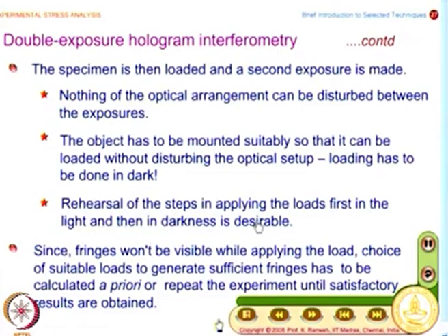So, when you want to record a hologram, you have to do this practice, and from the loading point of view, since fringes won't be visible while applying the load, the choice of suitable loads to generate sufficient fringes has to be calculated a priori or you repeat the experiment until satisfactory results are obtained. So, you understand experiments are not that easy, it is back breaking, that is why people want to minimize the number of experiments that they do.